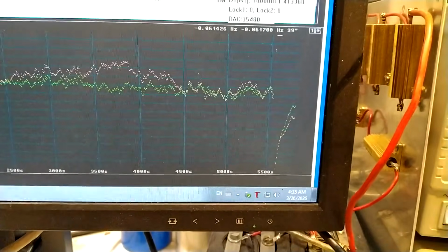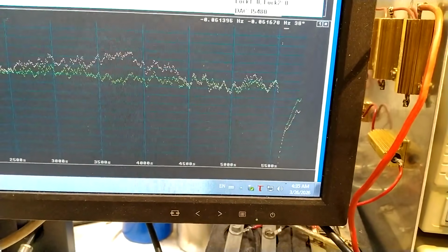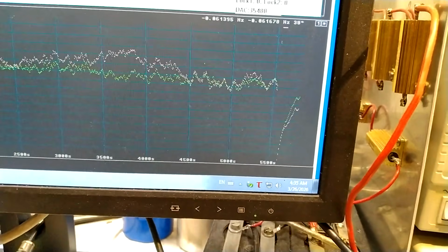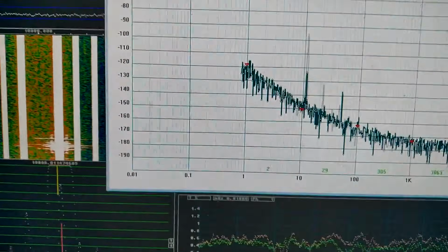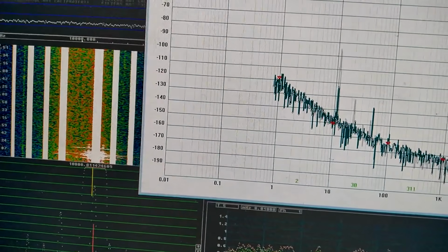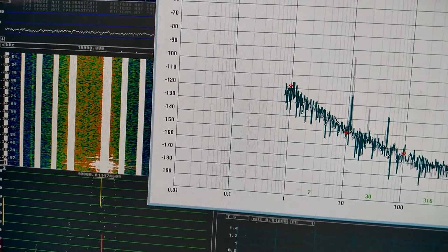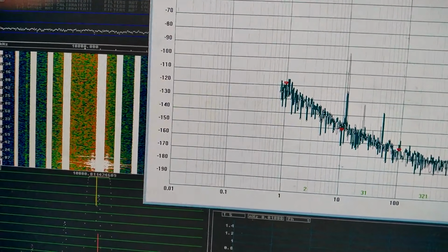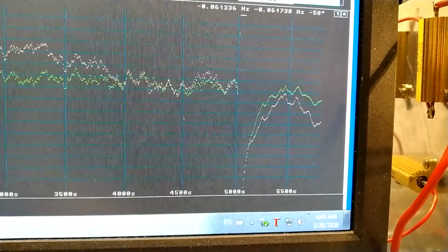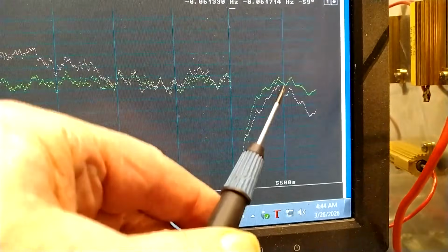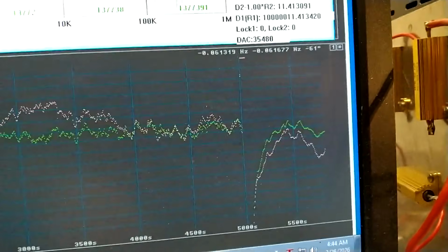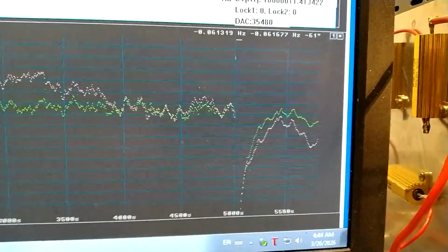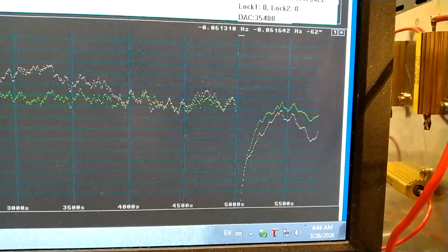I have increased the PLL time constant by a factor of 20. And it will take some time before it has stabilized, but it looks much calmer here. And when I look at the phase noise, it is now much better. It is probably becoming a little better than -120. With a PLL time constant, like you see here, this soft curve, this noise that I see on the Wenzel is the noise from my 4-crystal oscillator.